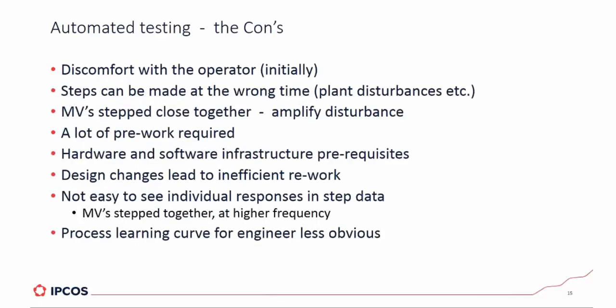The cons of automated testing. Of course, there is a discomfort of the operator and of the plant, and initially that could be quite a big effect. I guess usually after some time of auto step testing, when we have set it up correctly, this discomfort will disappear and the operator will get used to the idea of some program making steps on his plant.